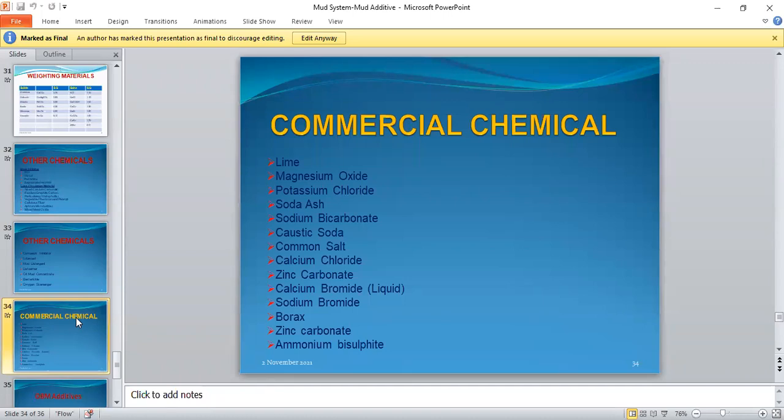Iron can form rust in the presence of oxygen. So there are 2 things that can cause your metals to rust. So you take care of them. You put corrosion inhibitor, you put oxygen scavenger. In the absence of oxygen, corrosion will not take place. Your pipes will be okay.